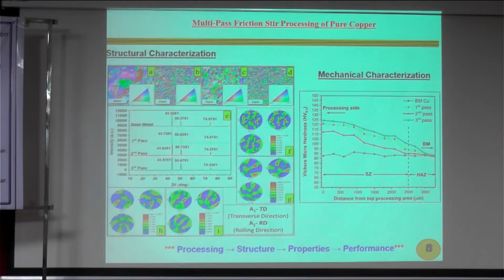But if you do friction stir welding, by severe plastic deformation we have changed everything. We changed the microstructure, and there is no need for shielding gas also, correct? But in fusion welding, we need a shielding gas. Again, for shielding gas you need to think which one to use, whether argon or helium.